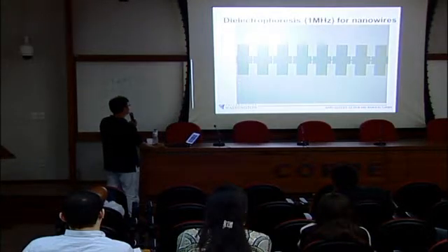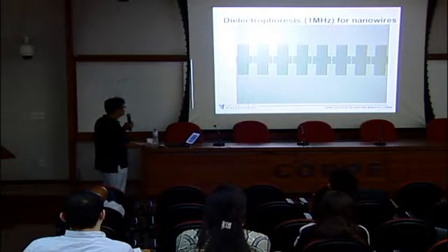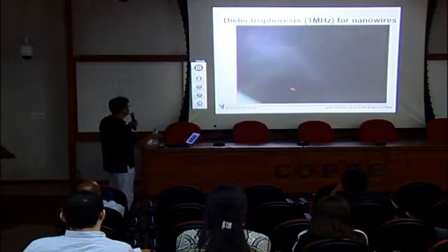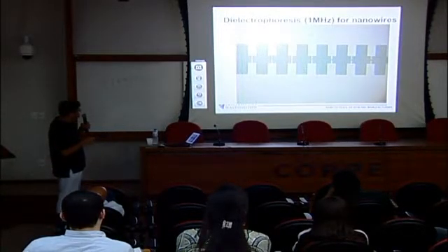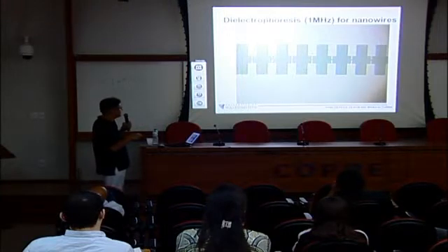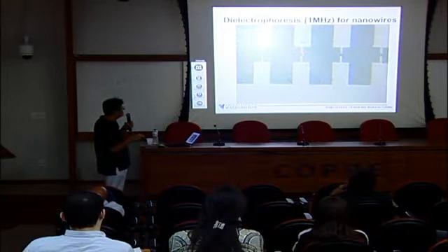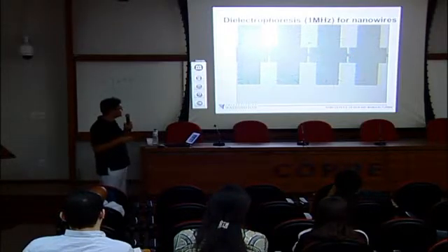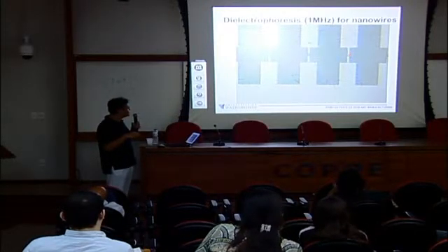So that's the electrophoresis. And then let's see the dielectrophoresis. At this time, we are applying a high frequency to generate dielectrophoresis. And again, the white area is the electrodes, and the green area is the silicon oxide insulation layer. So if you see, most of the nanowires are aligned at the edge where the electric field strength is highest. So they are deposited around the edge, and some of them will cross between two electrodes, because that's the gap where the electric field strength is the highest, right? So that's the dielectrophoresis. Here, we want to assemble the nanowires very precisely between two electrodes.